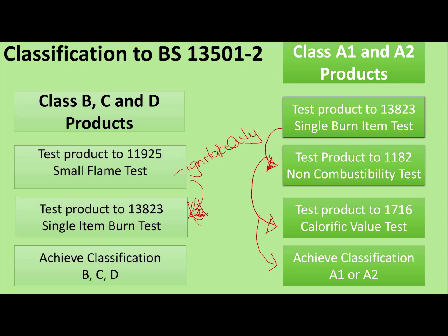So A2 is a similar kind of approach, and A2 in fire performance terms is very similar to Class B in relation to that test. Class B products aren't tested in accordance with the A1 and A2 products, so we don't know how it performs when the product is mashed up and put into a furnace. So we don't really know that.